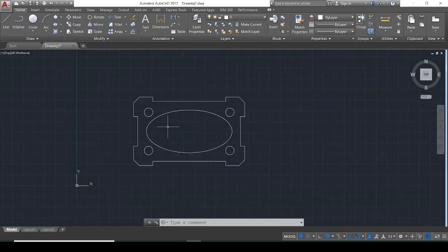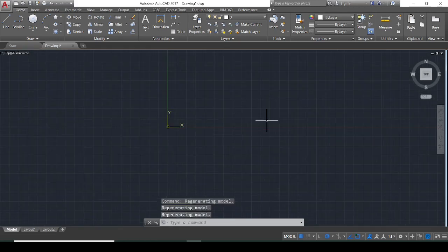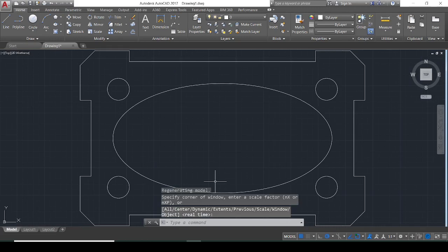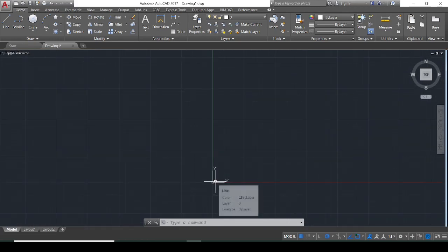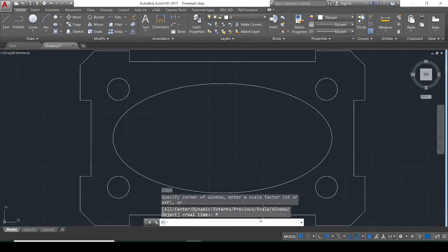There's also a possibility na zoom out mo, ang layo na ng drawing mo, click zoom extents to return. Or also, pag nangyari to, you can just click zoom and then previous. Babalik yung previous na command mo ng zoom.